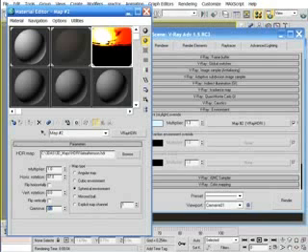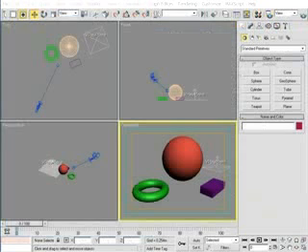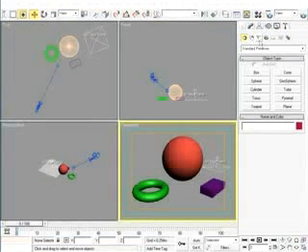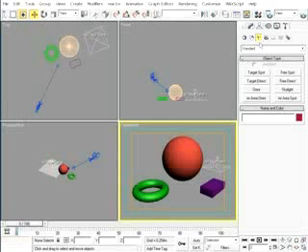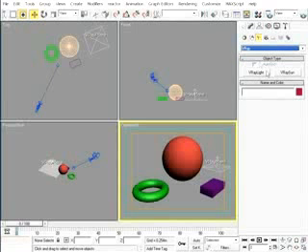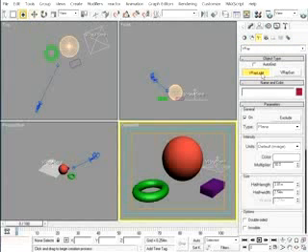Although I need to explain some other parts of it, other parts will be left for the next module. So the VRay dome light is accessed through the regular light icon in the command panel, and in the drop-down list simply click on VRay to display the two categories of VRay lights possible. There are 3 different kinds of VRay lights, and each is found within the type drop-down list at the top of the parameters rollout. After switching to the VRay dome light, just click once inside the active viewport and you have your light.